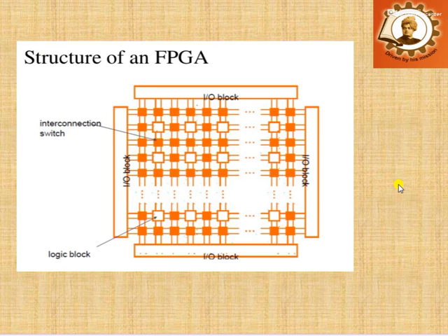That shortcoming can be overcome by using our FPGA. In an FPGA, you have a large number of pins, and depending upon its internal logic block capacity, you can implement a microprocessor and microcontroller inside your FPGA.